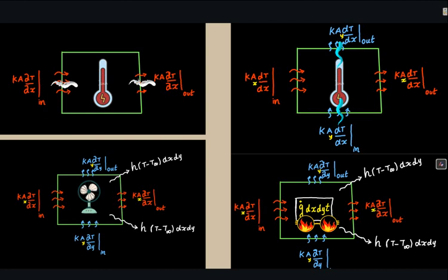And greater the temperature gradient, greater the quantity of heat that is lost due to convection. And h is the proportionality constant. We call that the convective heat transfer coefficient, that is h. So we assume that the convection is taking place on both the faces. The other face is represented here. It's not going to be visible, but we assume that the convection is taking place on both the faces.